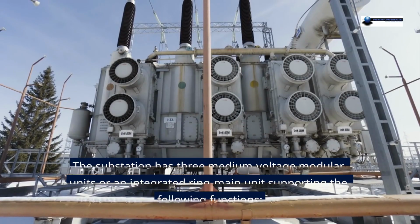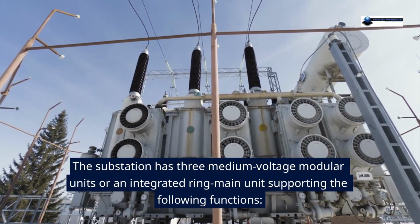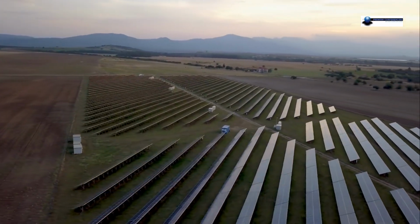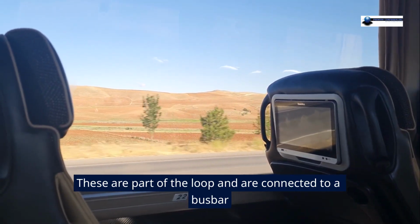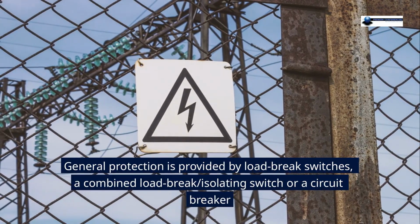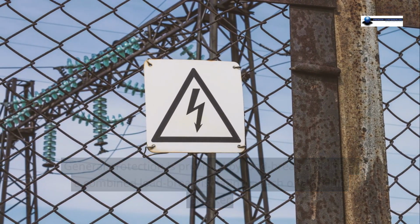The substation has 3 medium voltage modular units or an integrated ring main unit supporting the following functions. Incoming panels, each with a load break switch. These are part of the loop and are connected to a bus bar. Transformer feeder connected to the bus bar. General protection is provided by load break switches, a combined load break isolating switch, or a circuit breaker.